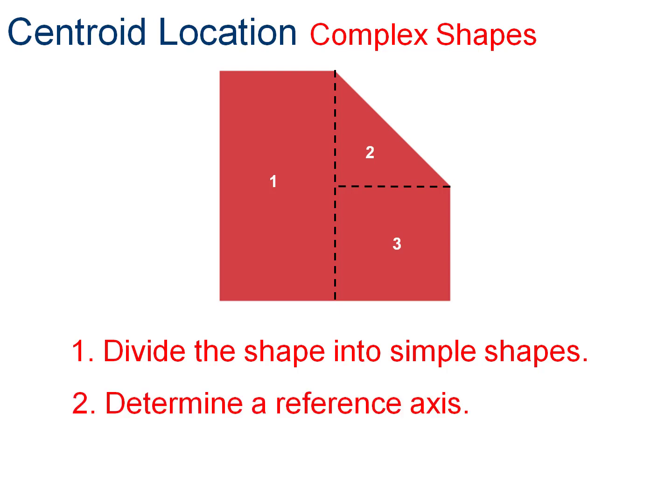The next step is to determine a reference axis. Now, most of the time, it doesn't really matter, so long as you're consistent. So I'm going to tell you for this one, for ease of simplicity, we're going to choose the lower left side. So that's our reference axis.